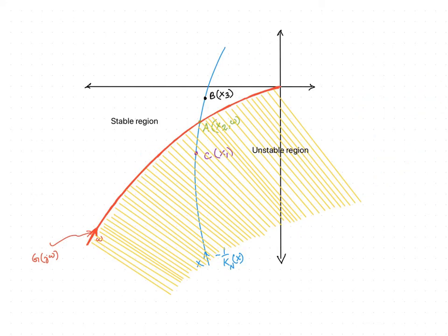As mentioned previously, the describing function method for stability analysis of a nonlinear system resembles closely the stability analysis method of a linear system by the Nyquist stability approach. In the Nyquist stability criterion, we find the number of encirclements of the critical point minus 1 + j0. Here, what we do is, instead of a critical point, we have a critical locus.